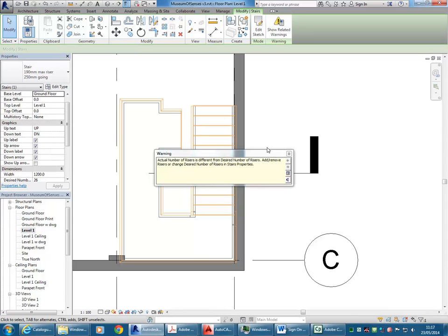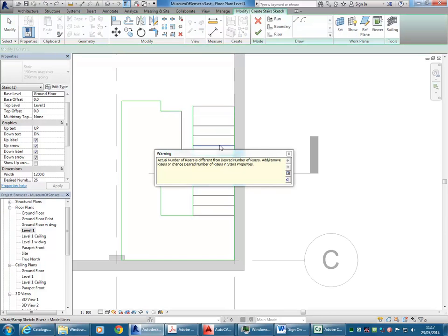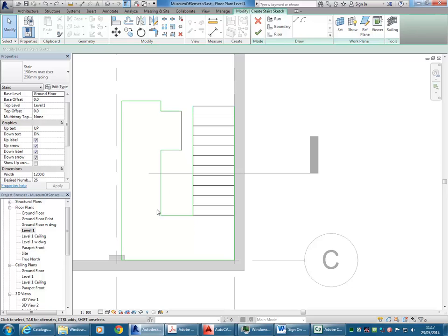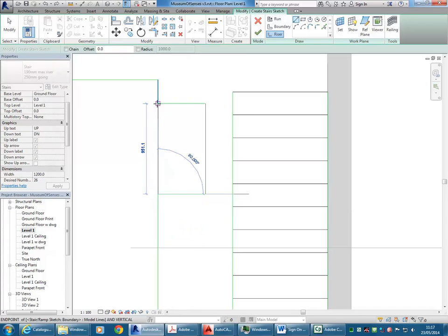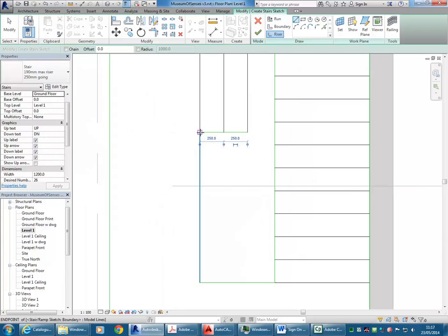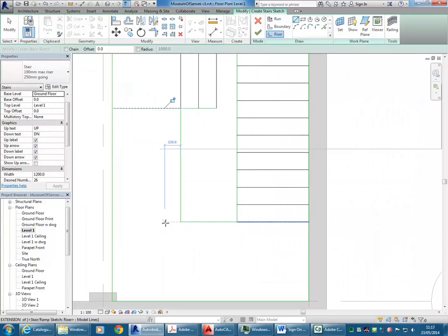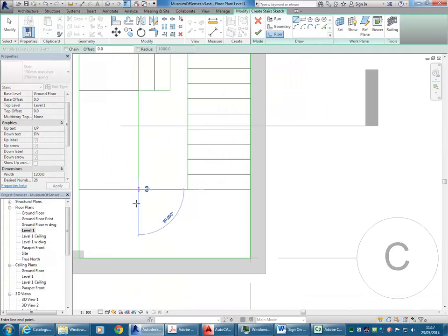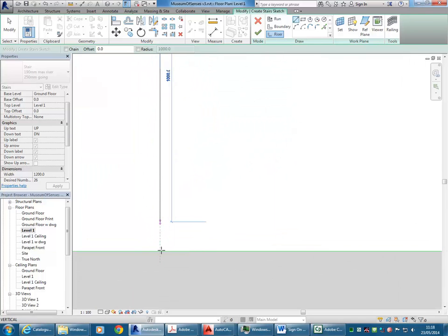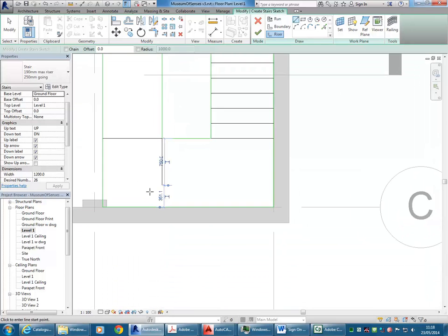So that's working now, which means the sketch is okay, and that it was one of those risers in there, which again means the AutoCAD was off. That's not uncommon with AutoCAD, unfortunately. But here I'm drawing in some new risers where I know I'll need them, and this is good to see actually, because this is how you would work out a stair. So from each of those landing lines, you would have a riser, and here again it's being difficult, so I'm just going to do it anywhere and sketch it out afterwards.